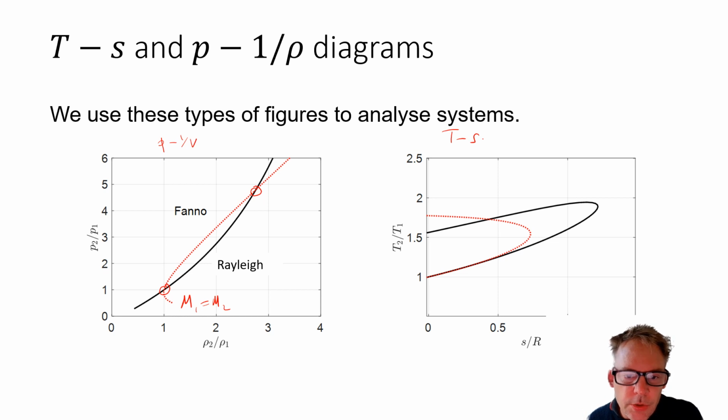And the other solution is the branch of supersonic flow becoming subsonic. And you can see these two solutions. The first solution here would give an isentropic relationship because the entropy is the same before and afterwards. The other one is where the entropy has clearly increased, demanding that the solution of subsonic to supersonic is rejected.